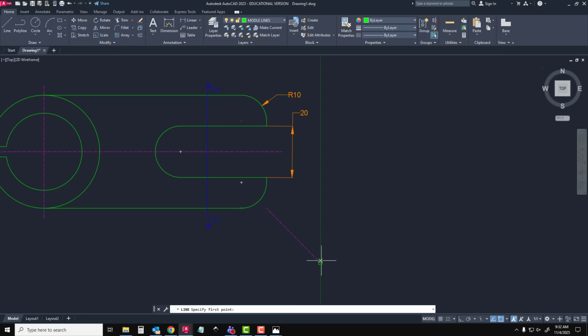So if I put my cursor right here and I start coming up, see how I put my cursor at both those locations and now it kind of did a sketch? Well, it's because of this right here. It's going to show the reference. So I come back to my spot. I'm going to click. I don't want it to be angled, so I'm going to hit F8 again. And if I want to, I can come up to here and come straight over and do that.